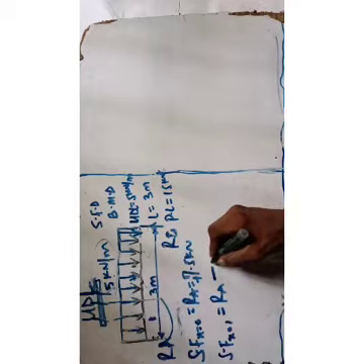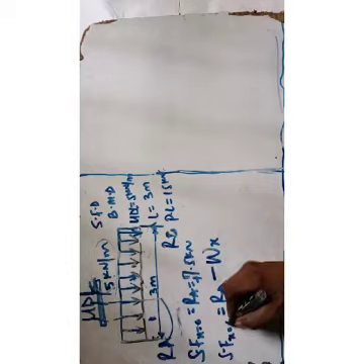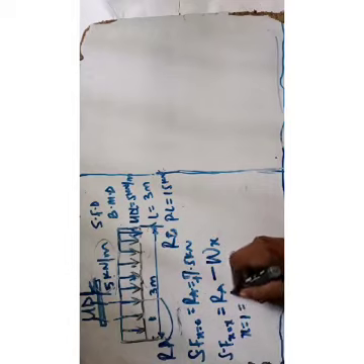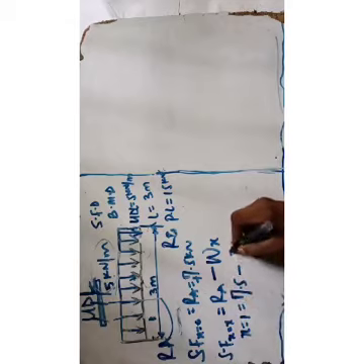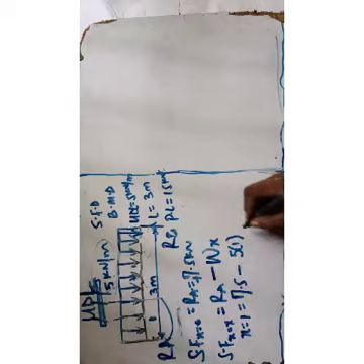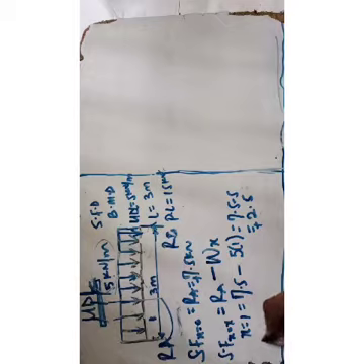So that is times wx, and that is when it is x. So therefore at x equal to 1, I'm going to have RA, which is plus 7.5, minus my w, which is 5 times 1, and that will be 7.5 minus 5, and that will be equal to 2.5. Okay, so when it is shear force at x equal to 2, that will also be equal to what?